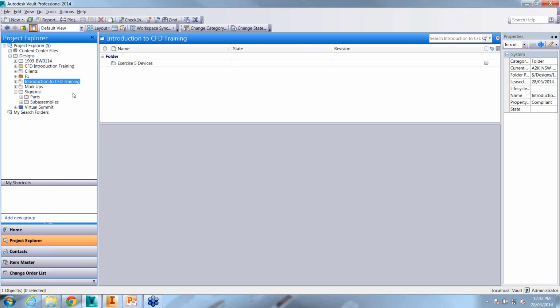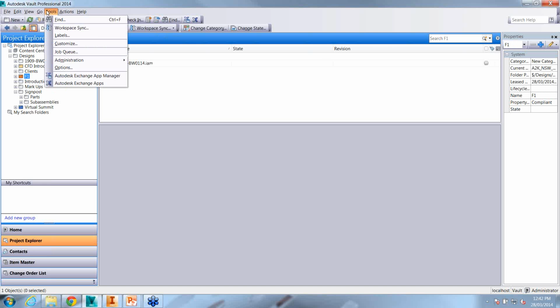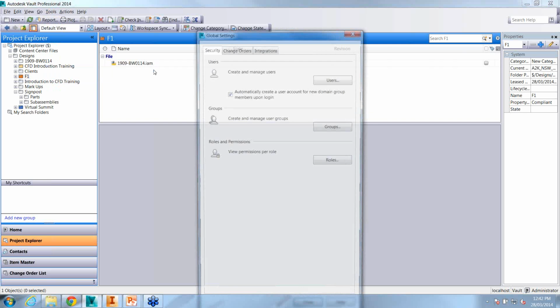Okay, so again, I covered off all the basic introduction stuff in the first part of this webinar series. So I'll move on to that topic list that we looked at earlier. The first thing on that list was how to create users and groups. So for example, let's say we're just setting up our Vault almost for the first time. I want to create a group, and the way I do that is I go up to Tools, Administration, and I go into my global settings.